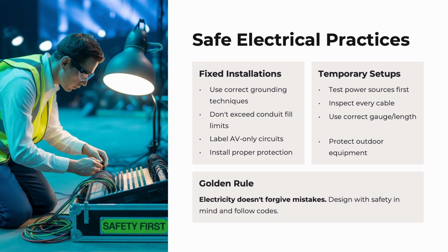In live production setups, test all power sources before plugging in. Inspect every cable one more time. Use the right cable gauge and length. Avoid overloading your circuits and keep outdoor gear weather resistant. And protect cables with covers and secure them safely.